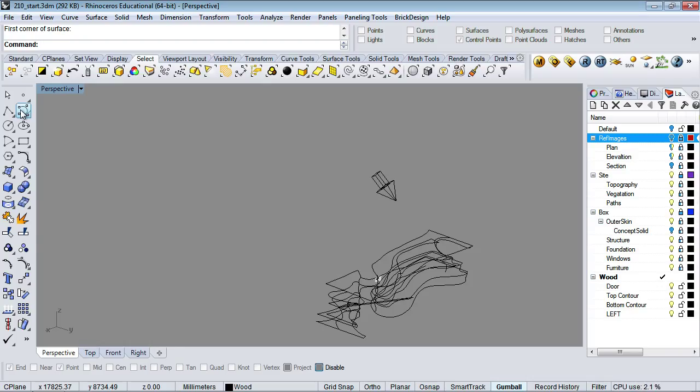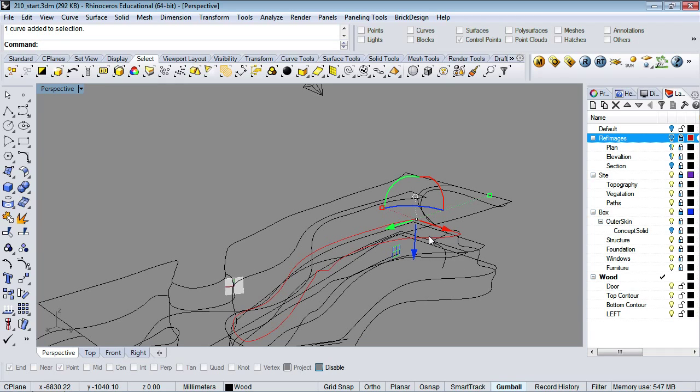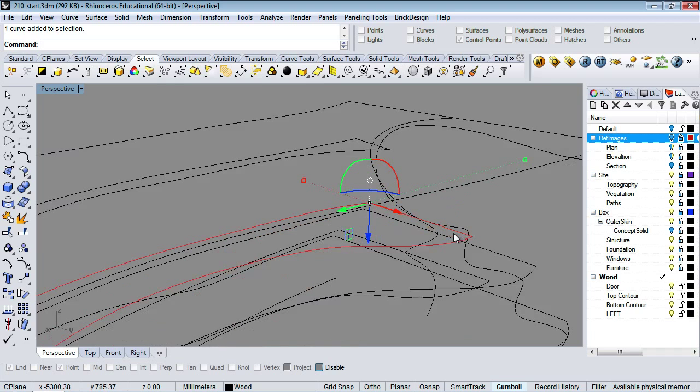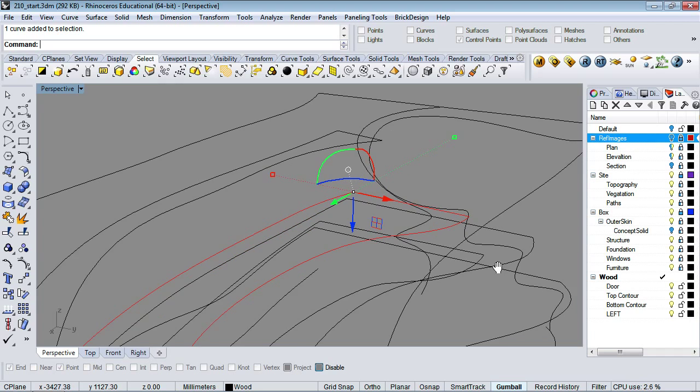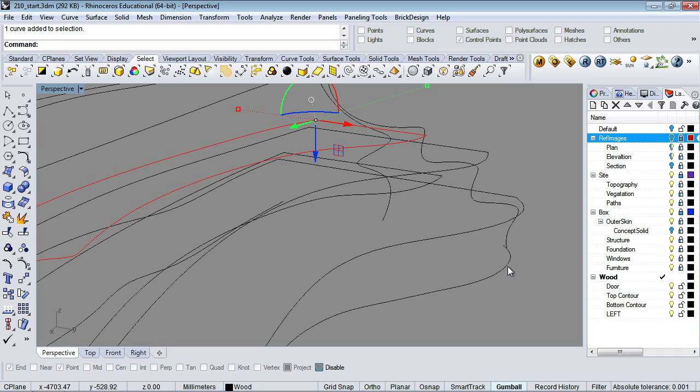Yeah, that's exactly it, I'm going to use the top and the bottom. So there are certain ones of those that are important. Where I think about where I'm going to cut that geometry, like here, actually, probably back here, I'm going to draw a curve on this transition that describes that, and that will be my top rail. Okay, so let's just say that that is where I'm going to cut it. That's going to be my top rail for the first one. This will be my bottom rail. And then this section between here and here is going to be my cross-sectional curve.